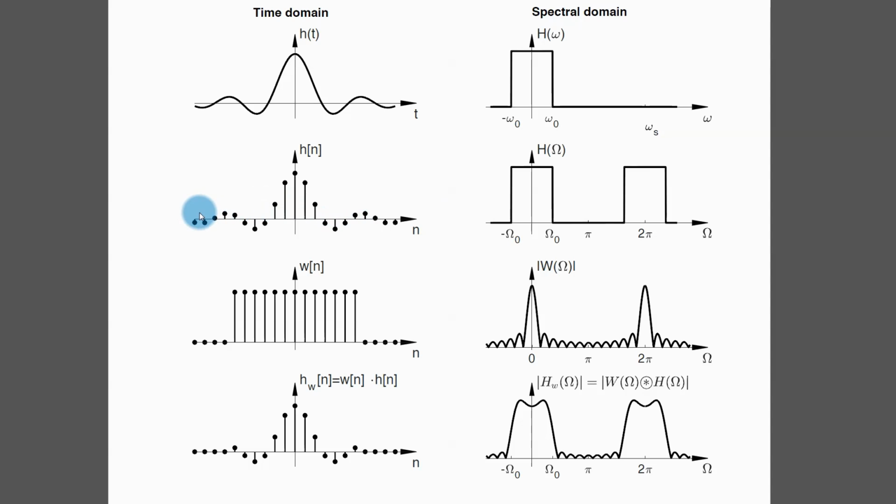Note that this frequency characteristic is quite different from this ideal but unrealistic case where the impulse response is infinite. This result actually troubles me. Here, in this stop band, where the frequency characteristic should have been 0, I do not have a 0. So these frequencies that should have not been passed are going to seep through, and the filtering is not going to be perfect. This is actually bad enough so that we do something about it.